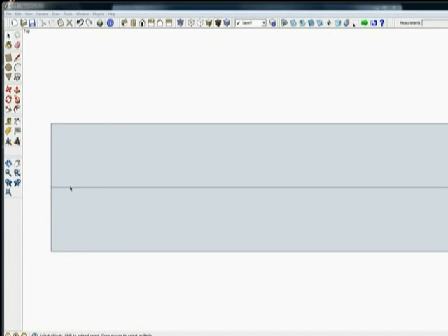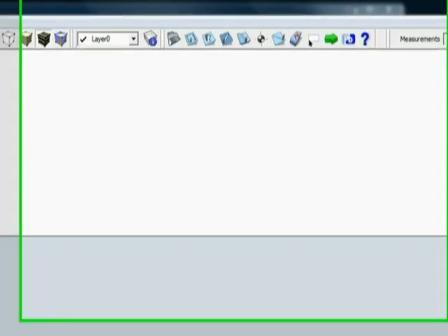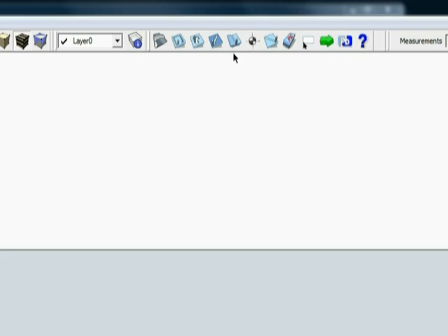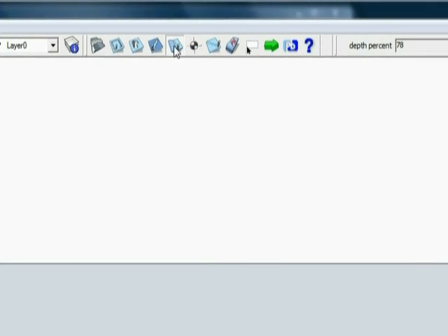But by removing material, it's going to more easily facilitate the bending of this foam. And we can let our flat printer do that, and our PhlatScript help us with that. We select the foam icon there, and we have an ability now to remove material. Now, if you go over here to our depth percentage, I can toggle through 4 different preset cut depths just by hitting my D button on my keyboard, and those are 100, 25, 50, and 75.